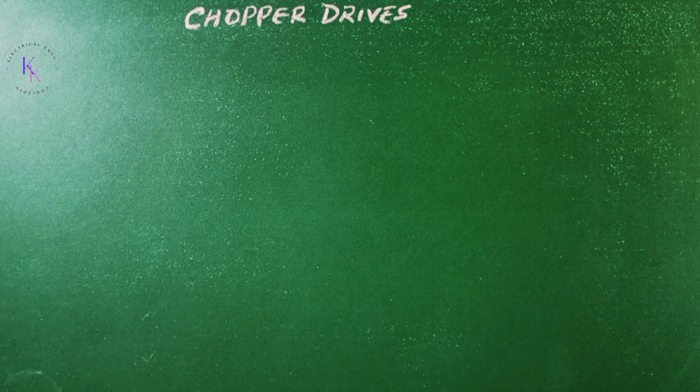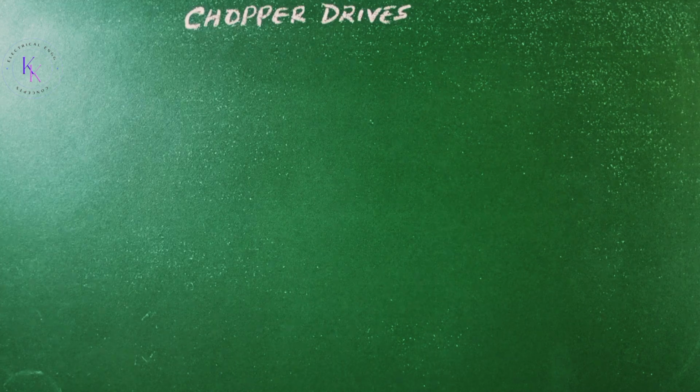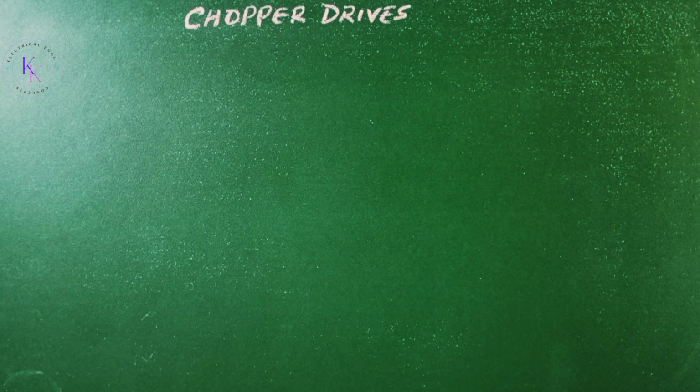Chopper drives. Chopper drives are widely used in traction applications all over the world. A DC chopper is connected between a fixed voltage DC source and a DC motor to vary the armature voltage. In addition to the armature voltage control, a DC chopper can provide regenerative braking of the motor and can return energy back to the supply.